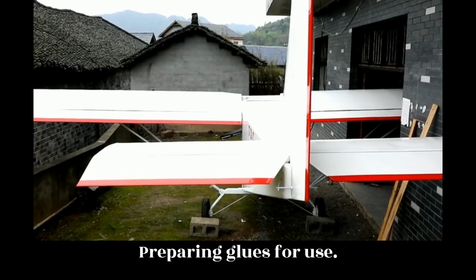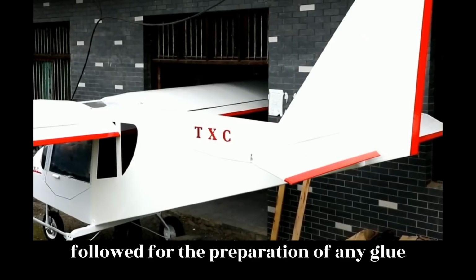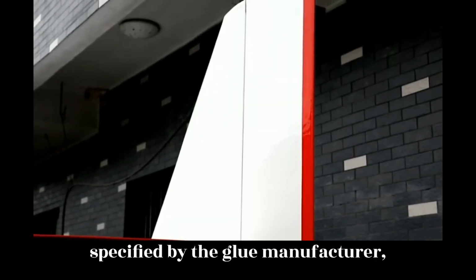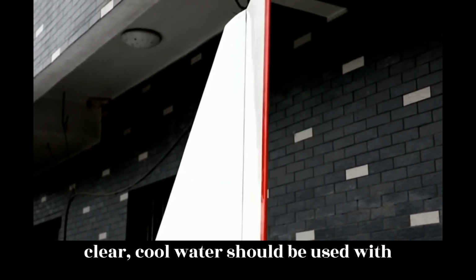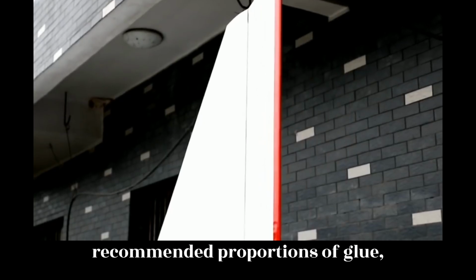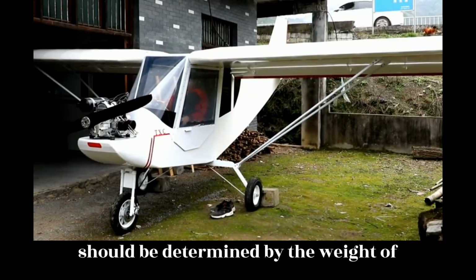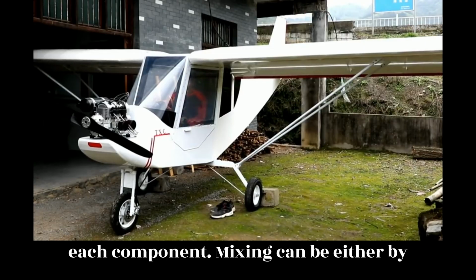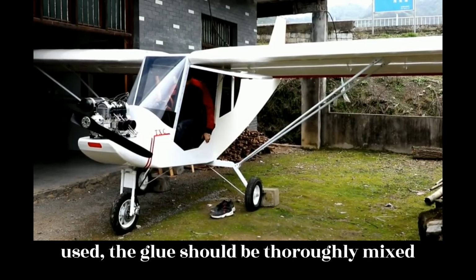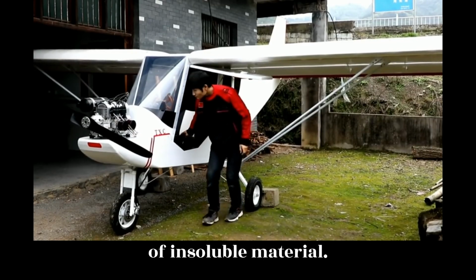Preparing glues for use. The manufacturer's directions should be followed for the preparation of any glue or adhesive. Unless otherwise specified by the glue manufacturer, clear, cool water should be used with glues that require mixing with water. The recommended proportions of glue, catalyst, and water or other solvent should be determined by the weight of each component. Mixing can be either by hand or machine. Whatever method is used, the glue should be thoroughly mixed and free of air bubbles, foam, and lumps of insoluble material.